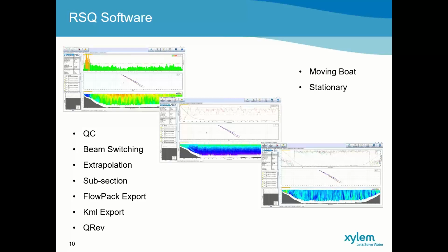The advantage of using QC is to ensure that while you are doing the measurement, you are conforming to at least the USGS standards, and that if there are any significant warnings coming up, you should rather identify the problem and resolve it, instead of just continuing to measure and collecting bad data.